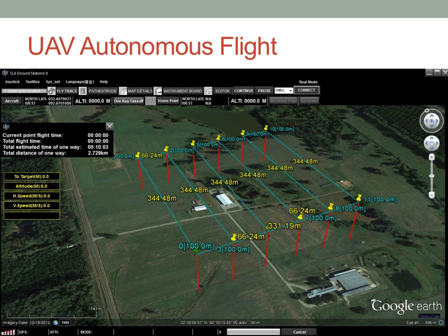You can do it while it's flying, on the go. You just hit upload, and your computer transmits it to the device, and then you hit go, and it goes from manual control to automatic control, and then it'll fly those flight lines. And then when it gets done, it'll return home and land, or you can take control of it and send it on another flight plan.